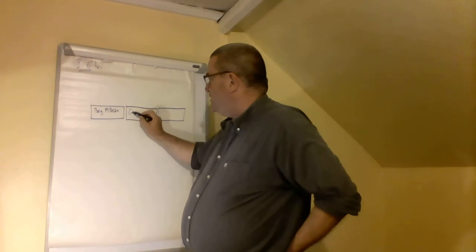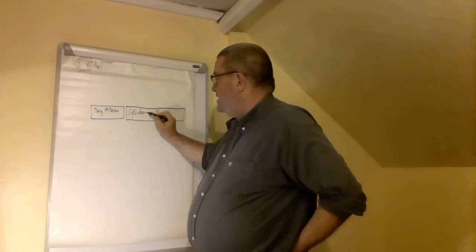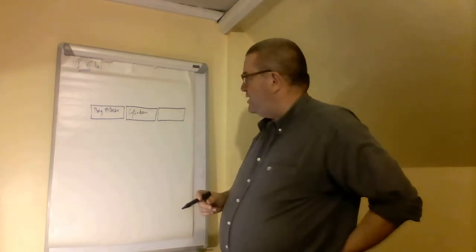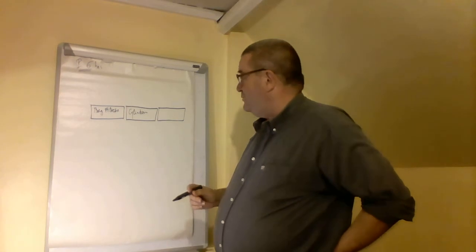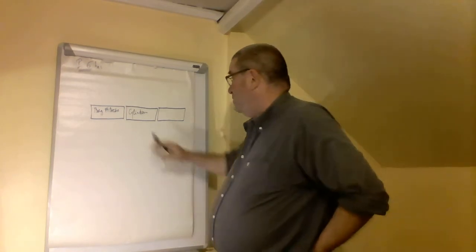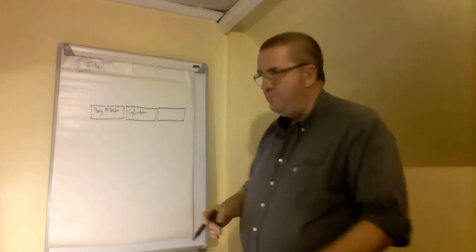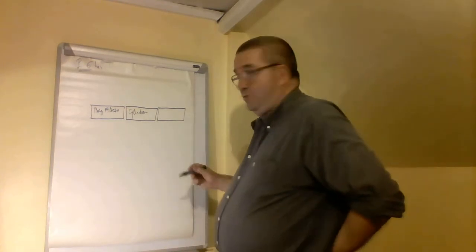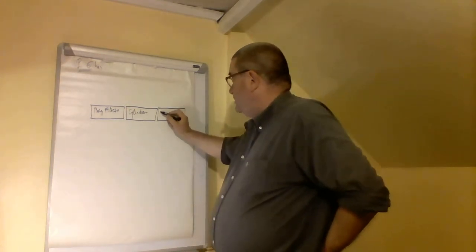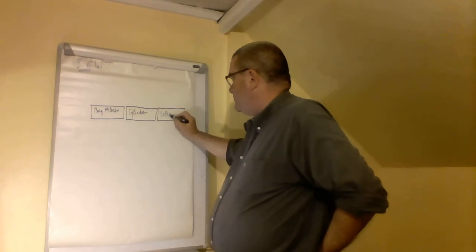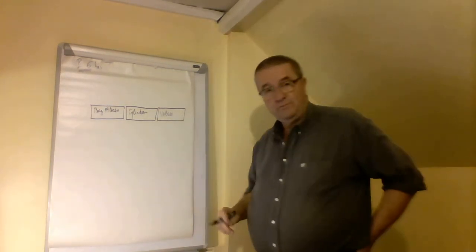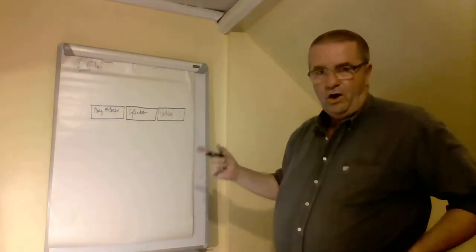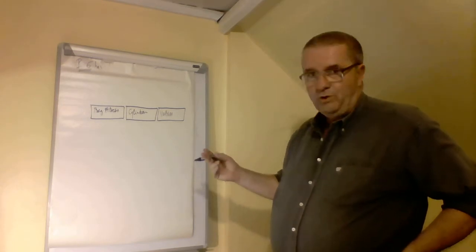We had also cylinders. They would need a bit more pressure. Very often cylinders are the first components which are blocked by a lack of pressure, and they really dislike liquid water. But normally it's possible to have a local treatment to remove liquid water if there is dysfunction of a dryer or no dryer. And then valves, regulation valves. They don't need pressure, so they are very different from the rest, but they do need a very good air quality, no dust, no oil, no liquid oil, and no liquid water.